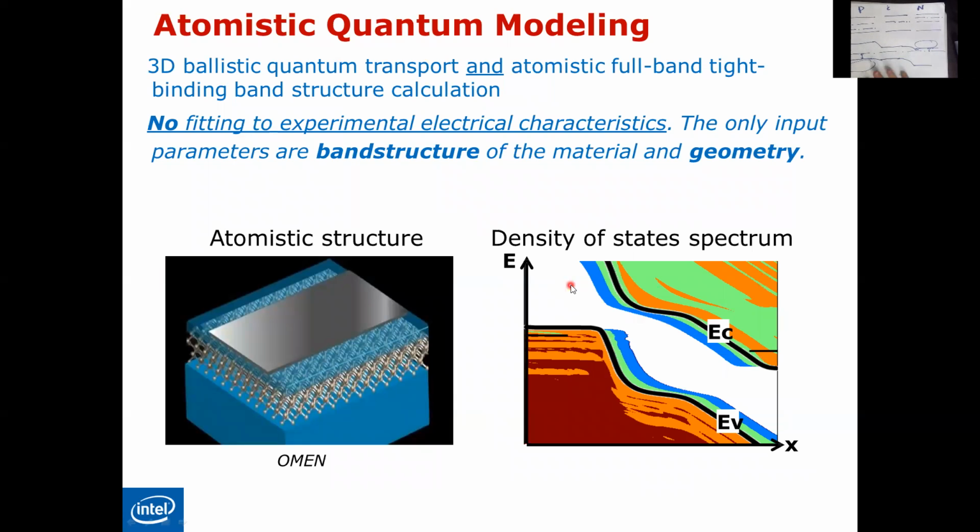If you remember, in my lecture number 4, the last lecture in the material part, in the last slide, I mentioned this. Whenever we go narrower than 1 micrometer, we have to kick out the classical or semi-classical drift diffusion model, and we have to use an atomistic quantum model for the tunneling field effect transistor. Again, this is also for your knowledge.